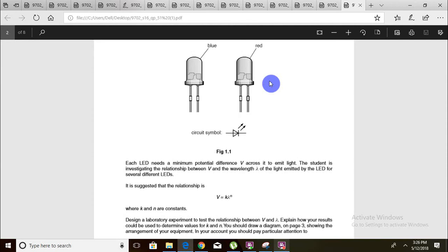How do you know that light is being emitted? It could be emitted, but with very little intensity and would not be visible, or you may need some sort of a standard. So you can use something like an LDR that has been calibrated, or a photometer.